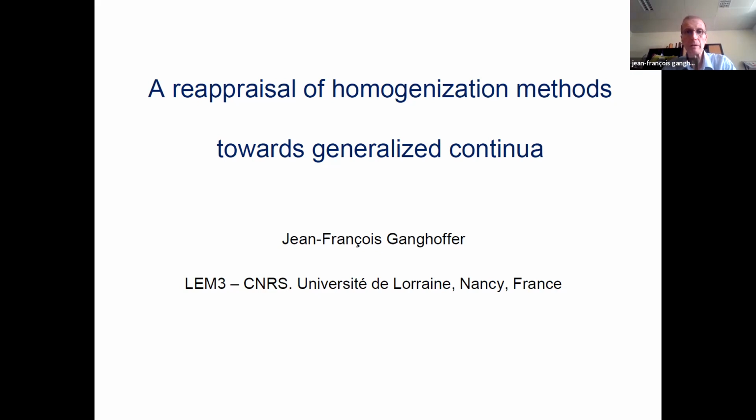So indeed, I will speak about recent works dealing with homogenization methods towards generalized continua, and the need for this arises especially if we have metamaterials which are prone to exotic behaviors that we cannot reach with conventional materials. So I will not show you a lot of pictures because you all know a lot of examples of mechanical metamaterials and the kind of responses they can exhibit, like auxetics, which have negative Poisson ratio, or pantographic structures which are prone to strain gradient effects with nearly no Cauchy elasticity.